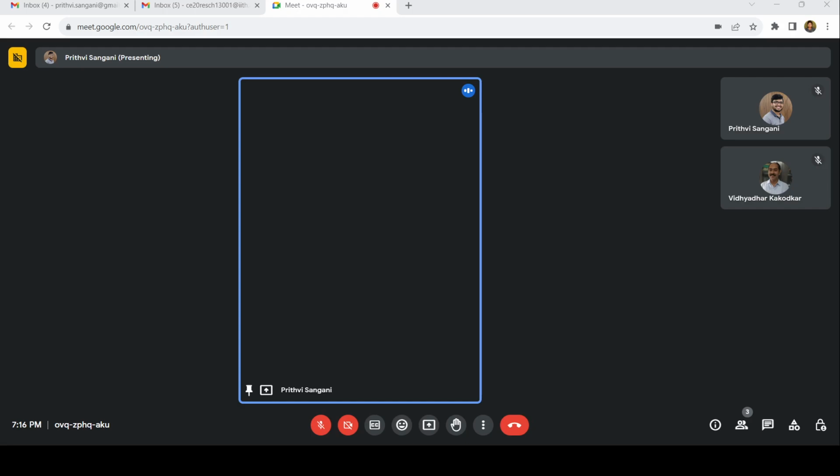So let us solve for the support reactions. We'll have P directly here. So this is L by 2, this is L by 2. It will generate an opposite force in this direction, which is P, and the bending moment is PL by 2.